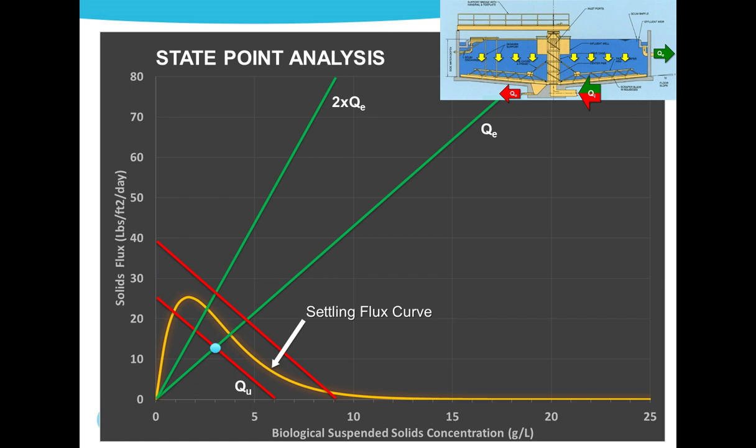They're changing. Variations in the solids characteristics occur in the natural course of operation. For example, due to changing COD loadings, conditions that promote filamentous growth, changes in sludge age, all of which occur in normal operation, can shift the flux curve and impact settling. These variations are considered, and we do consider them, as part of the clarifier design process.